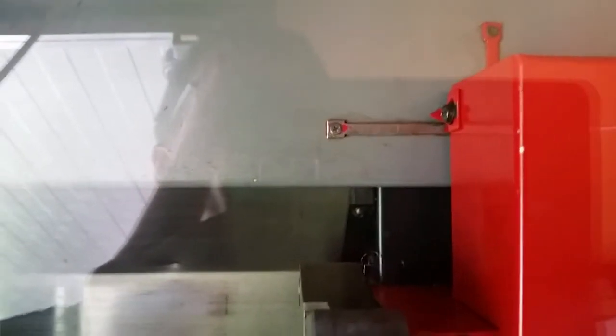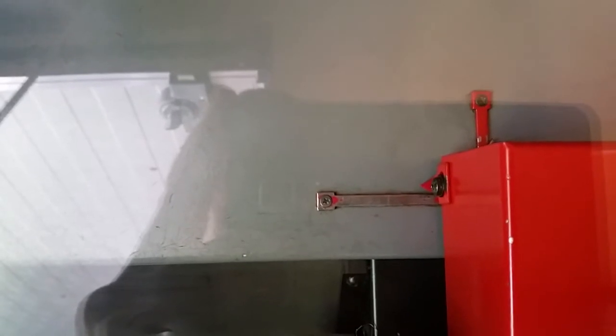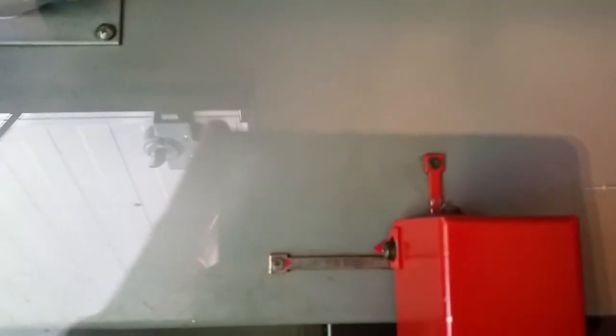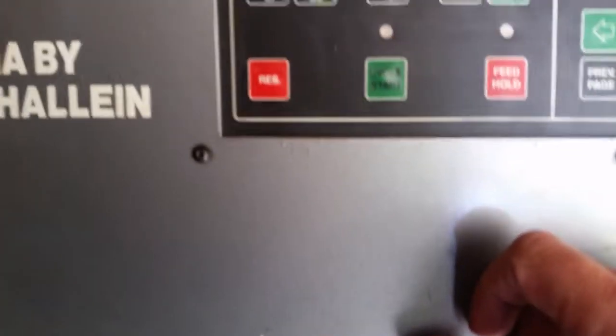So that didn't go too well. The reference position should be slightly lower for the x-axis. So let's put the machine in manual and jog it to where we're happy to start. So this is exactly why I try to leave the machine in a good position for referencing. So that should be good. Let's try the reference mode again. Same deal. Push cycle start when we're ready, and the arrows should go to the top and right side of the crosshatch. That looks better.